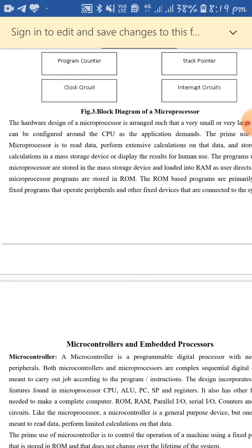System on chip in the sense it contains on-chip RAM and ROM. You can see the block diagram of a single chip computer. That's why it is called a single chip computer. It has an on-chip central processing unit, and a particular amount of RAM, ROM, and a number of IO ports, timers, and serial ports which are required to perform particular specific applications.